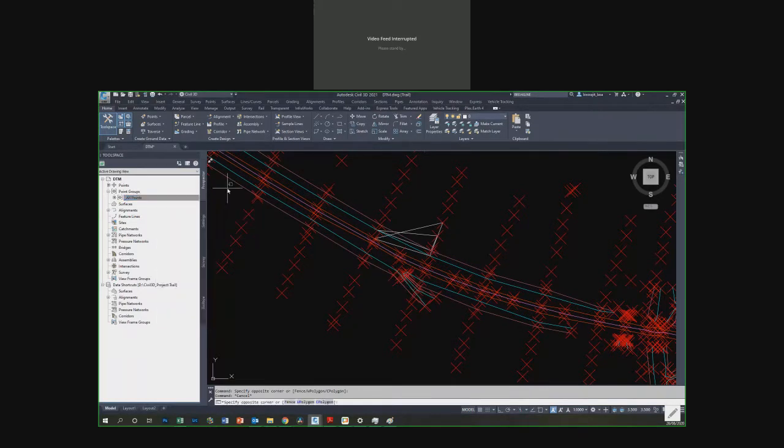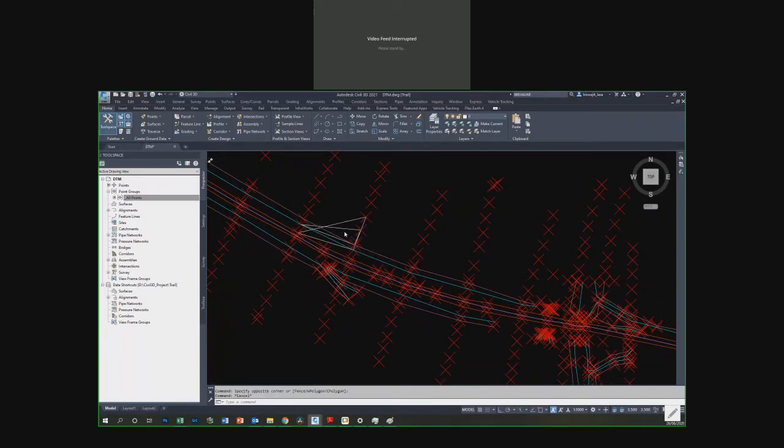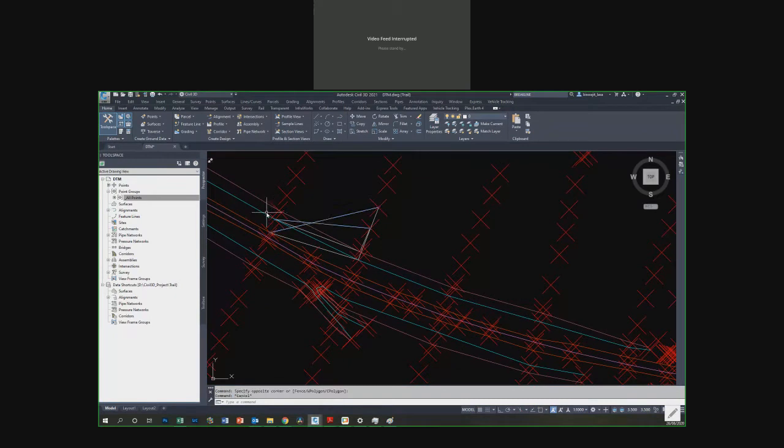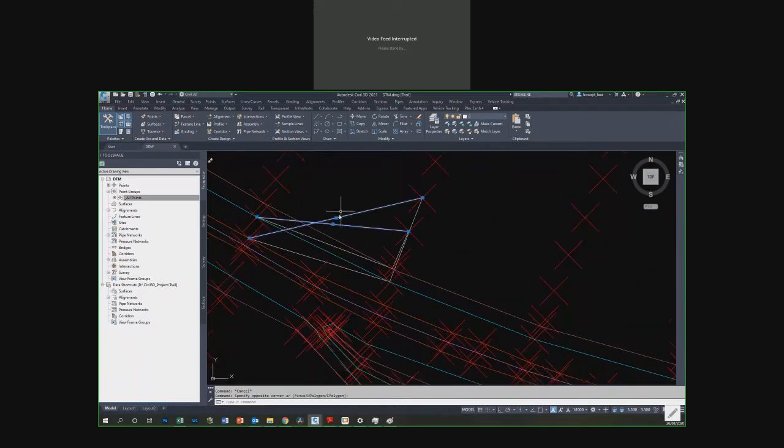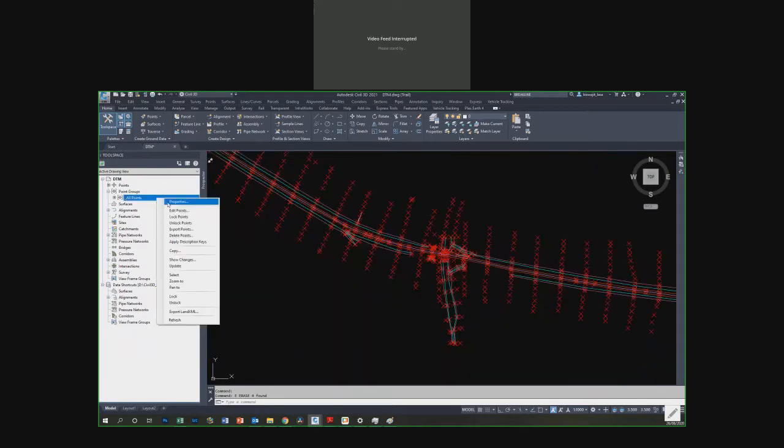Then there are n number of other things. One is also there which you will not use, that is a wall type. That means you will triangulate only on one side, and on the other side there is nothing. That is considered a wall type of break line, but you don't need them. So just switch it off again.